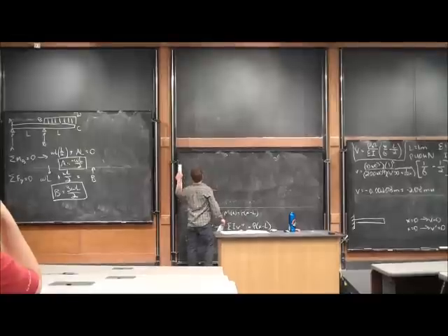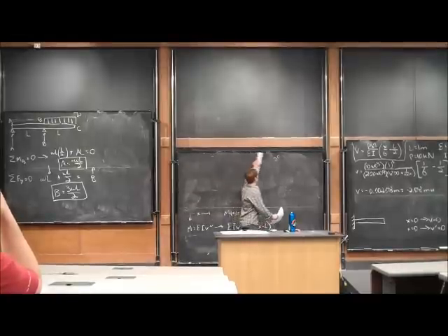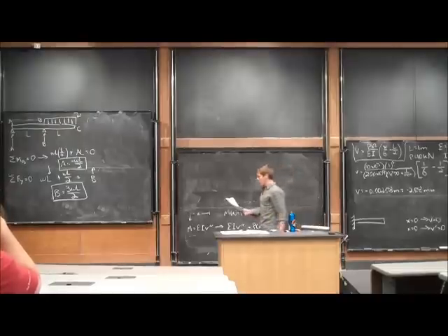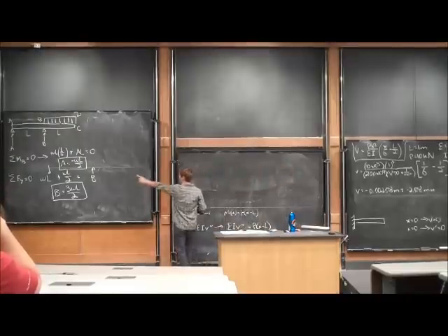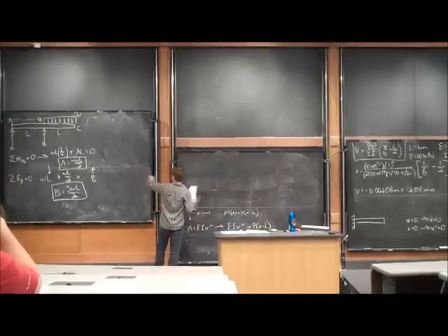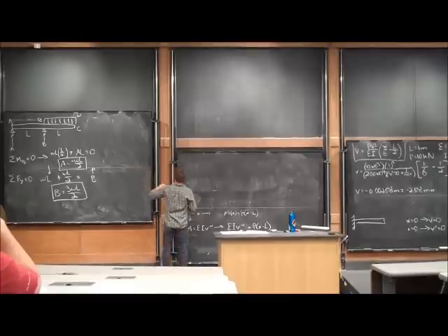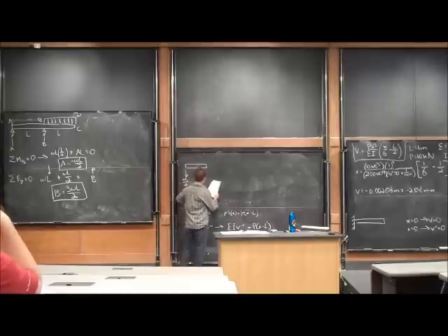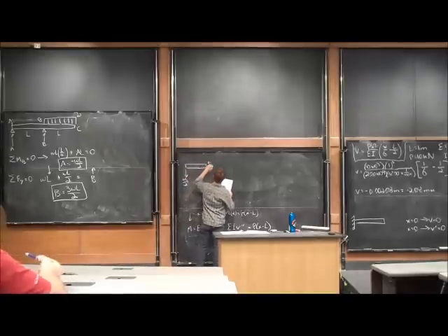So the first thing we need to do is solve for the moment equations of both sections, section 1 and section 2. I can do that by making a cut in the first case before we reach the second pin joint. So we have some beam, it's got a negative A force equal to WL over 2, and we have some moment acting in this location.